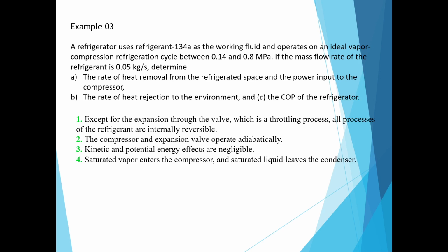So all the processes are reversible. The compressor operates adiabatically, that means isentropically, right? Adiabatic means, again, no heat transfer, only work is involved. Kinetic and potential energy effects are negligible, and saturated vapor enters the compressor. Now this is important: what enters the compressor is saturated vapor, 100% gas, and the saturated liquid leaves the condenser. So with that we will work on the example.